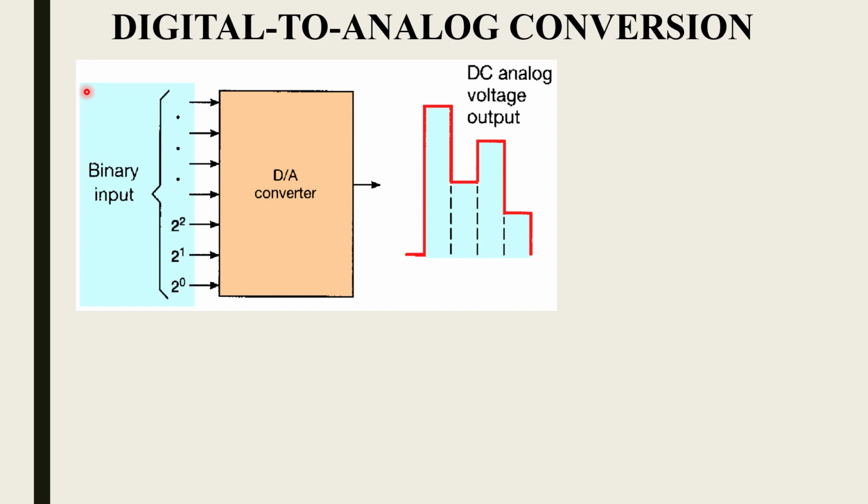A good example in video is where you're watching a car, and as the car changes speed, it looks as if the wheels are going backwards, even though the car is going forward. This is a result of aliasing, and it has to do with the sample rate, because when we're filming, we're basically taking samples of images. If we're not taking those samples fast enough for things that are changing, we'll get things that aren't there. So apparently that wheel is slowing down at a rate faster than we're taking pictures, and because of that, the changes that are occurring look distorted, and we get that effect in that particular case.